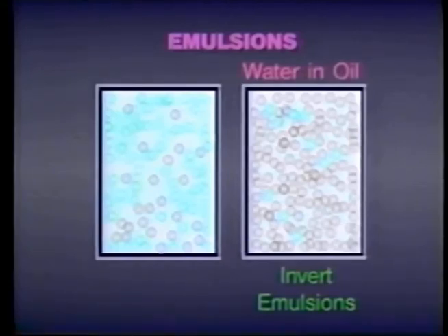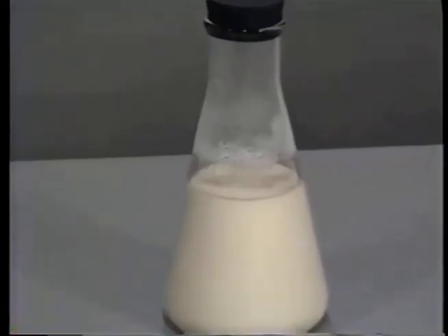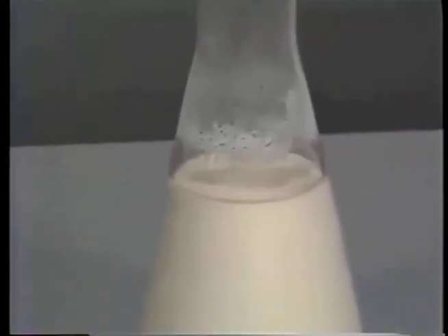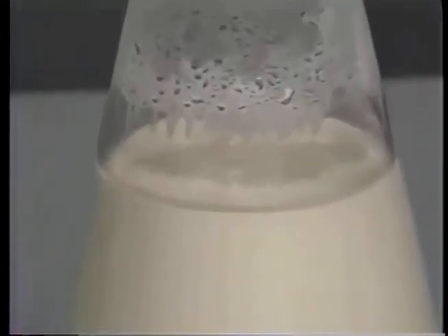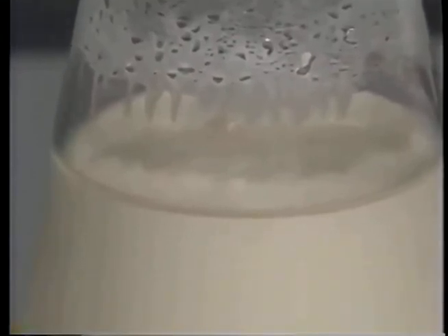But because they contain more oil than soluble oil fluids, they provide better lubrication. However, the oil and water in an invert emulsion tends to separate out easily, especially when the fluid is stored or used at low temperatures. Separation of the emulsion is easy to spot if you let a sample of the fluid rest for a time.